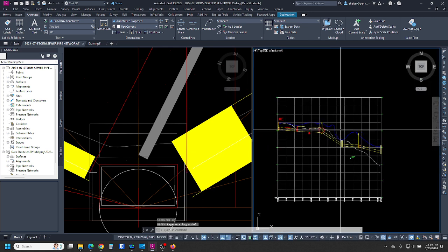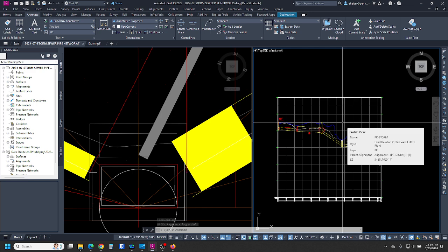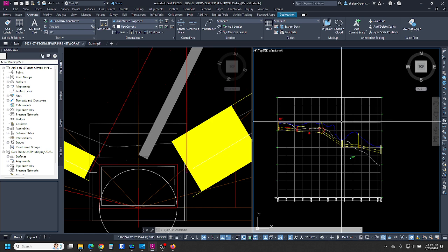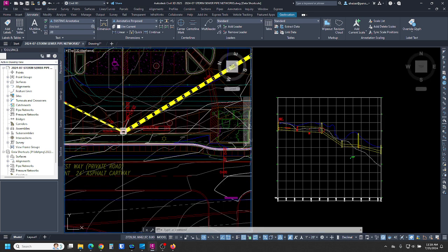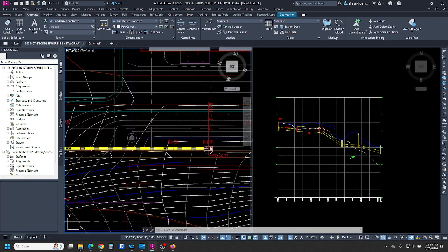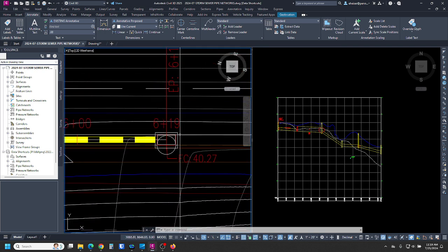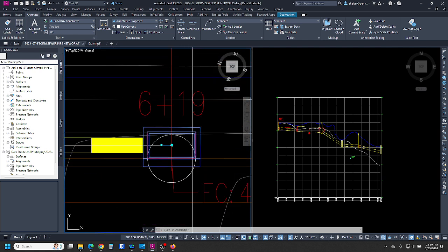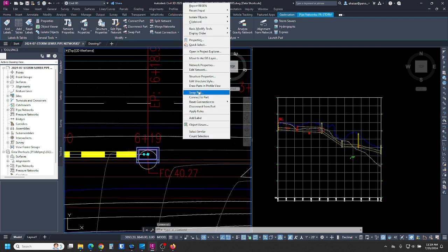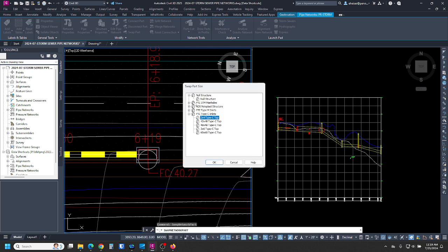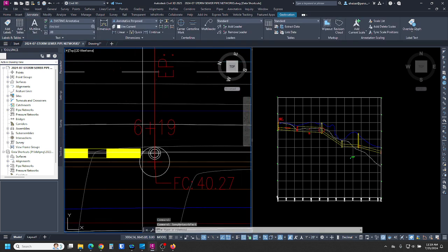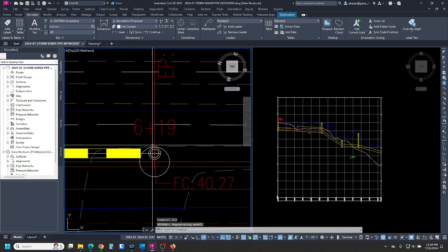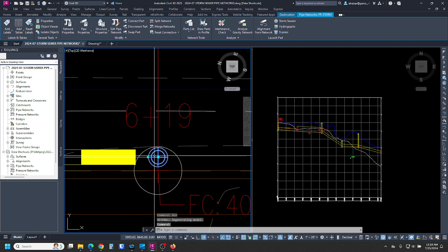And keep moving forward. So that's how you swap pipes. If you have an outfall pipe or something and you want to make it a null structure, same process. We'll pretend for a second that this is an outfall. So I'm going to click on the part, swap part, and I'm going to change it to a null structure and hit OK. It puts regen. It puts this block here.